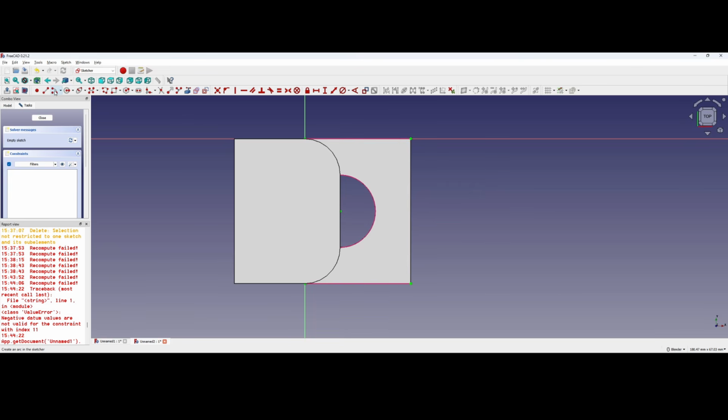Now I'm going to use the arc tool with the center and endpoints mode selected. I will select our center point on the circle, and I will bring this arc tool out until it touches our reference line, and bring it through and click on this other reference line here. And so that's created an arc for us.